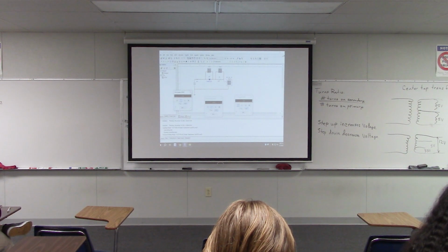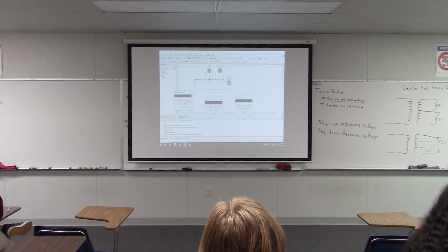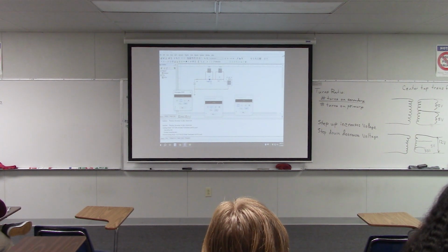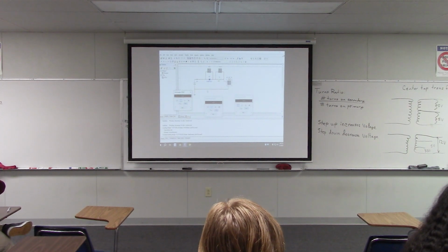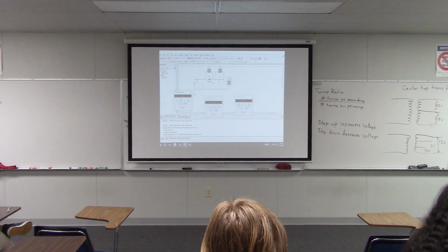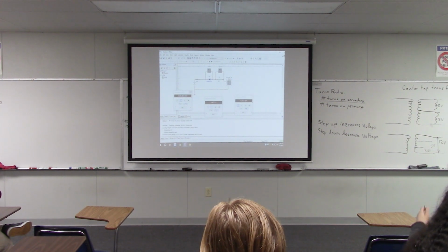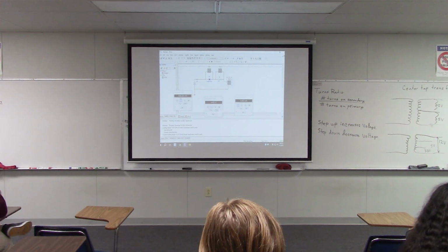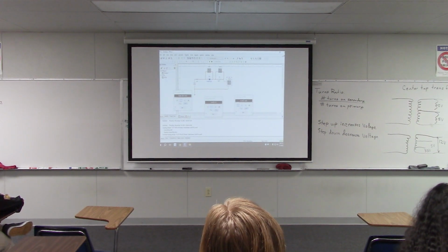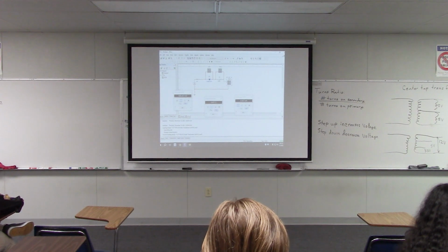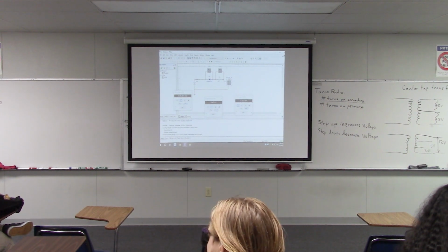So what voltage do we expect? First of all, is that diode forward biased or reverse biased? Forward biased, exactly. So what voltage do we expect to see across there? Yeah, about 0.6 volts, something like that. So we can run this and just check. Yeah, and sure enough, it's about 0.55 volts, something like that. And so then the rest of the voltage is across the resistor, and we can see the current there.